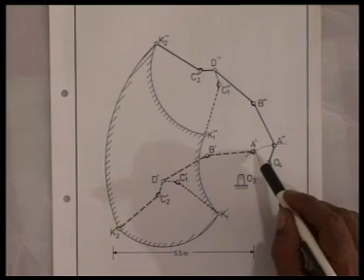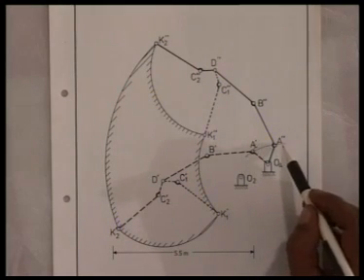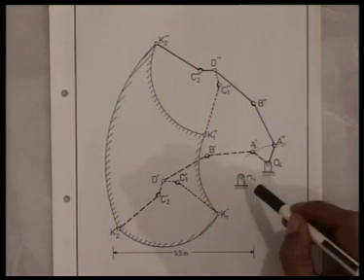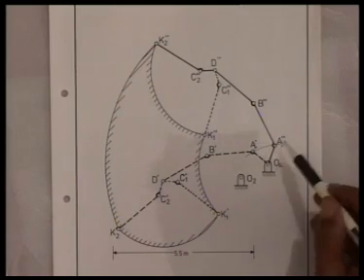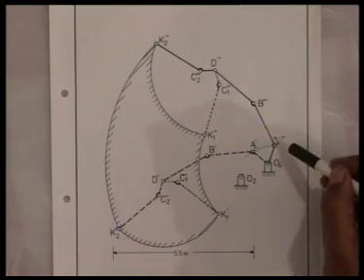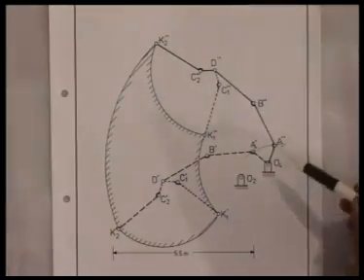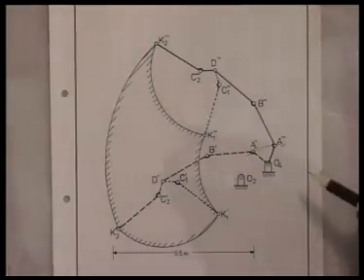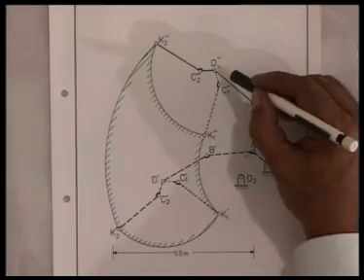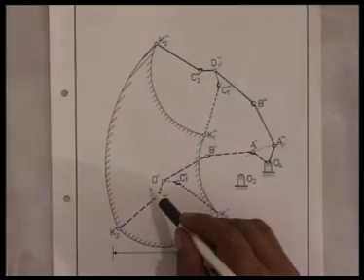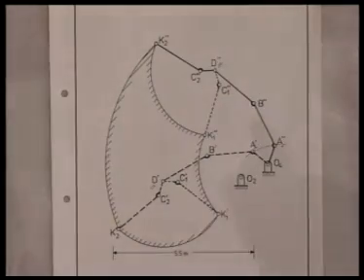So, I can locate the position of A for the extreme movements of this actuator Z1. O4, A, B and D, all four belong to the same rigid body. So, using the tracing paper technique that we have just now seen, I can locate the corresponding position of D as D prime and D2 prime.